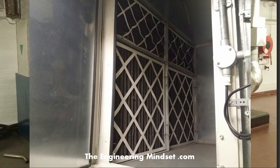So this is how they look inside the AHU. You can just move them, they're very light, and you can slide them out like this. Sometimes they'll have these clips here, so you can't slide them out. You just rotate these and pull the clips off, and take the panels out by rotating these.